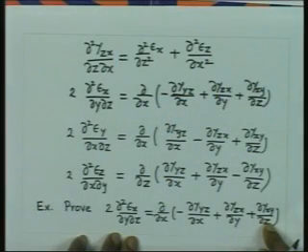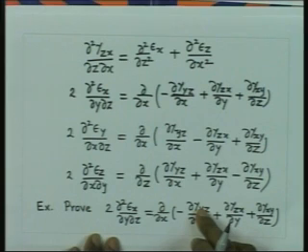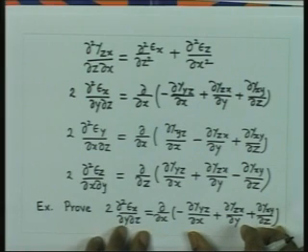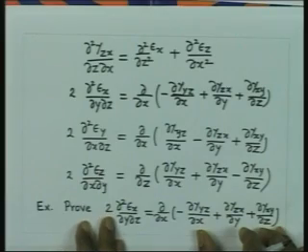In order to do this, what you have to do, you just take the expression for gamma xy, differentiate with respect to z, and then take the expression for gamma zx, differentiate with respect to y, and similarly take the expression for gamma yz and differentiate with respect to x, and then take this sum, and once you take that sum, you will find that you are going to have a relationship involving some expression which will finally lead to this left hand side.